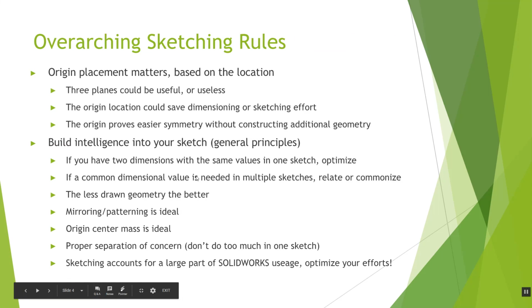Back to my presentation. All right, so origin placement. We talked about that a little bit. 3 planes could be useful or useless. If I throw them down in the corner, if I throw them in some arbitrary place. I mean, I've been around consulting, and I've seen some really, really weird things, like the origin randomly in the center of a rectangle, the rectangle dimensioned appropriately, and then an arbitrary 8-place decimal dimension from one edge of the rectangle to the origin and the other, because that's where the rectangle was when I drew it. Okay, I mean, just total arbitrary. The planes in that instance are benefiting you nothing.